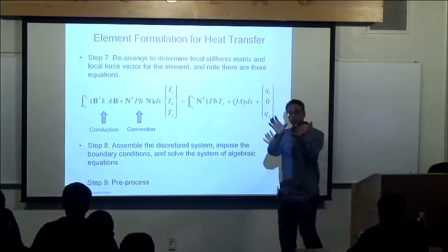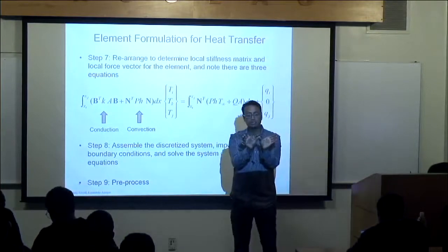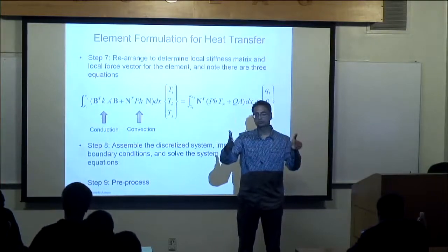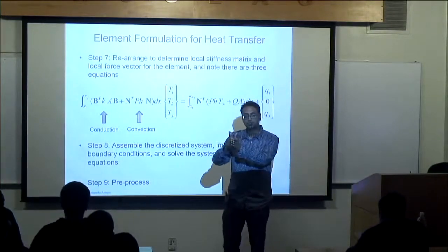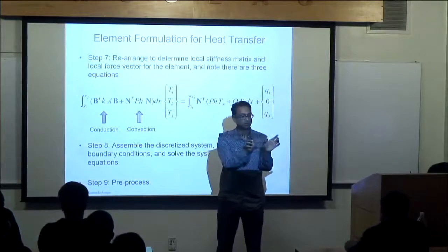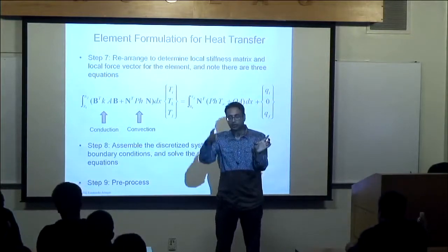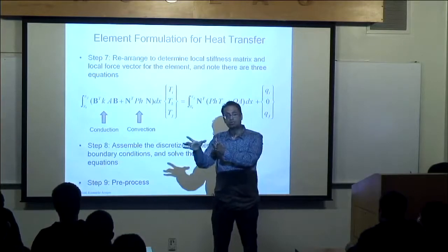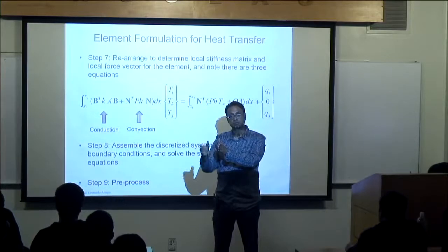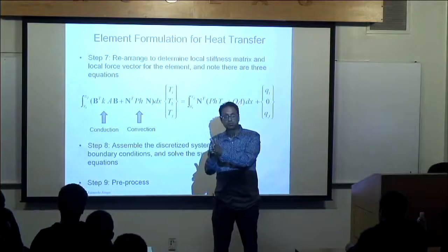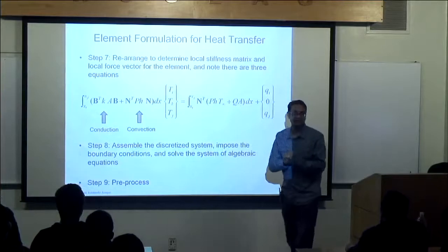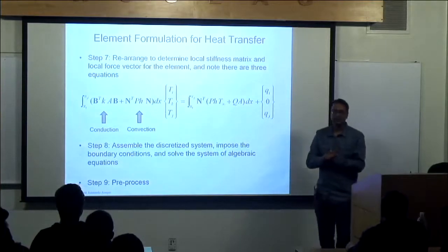So if you have multiple elements now, right? Let's say the first 3/4 of the material is steel and the remaining material is aluminum. Well, then I'll put elements here, and I'll stop right there where the aluminum and steel boundary is, and I'll put a new element that represents the aluminum. And for aluminum, I will use the appropriate conductivity. For steel, I will use the steel one. Thank you for giving me a good homework problem. He just gave me a great homework problem.